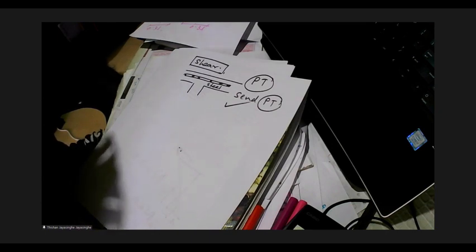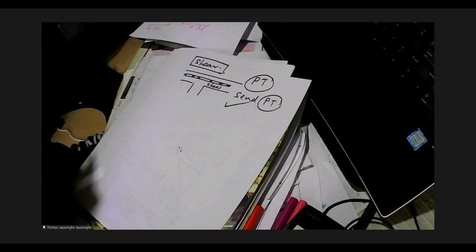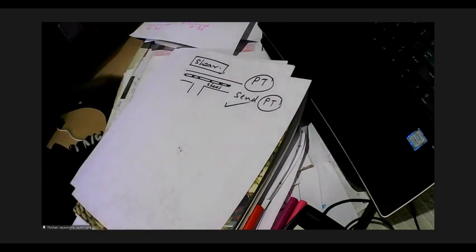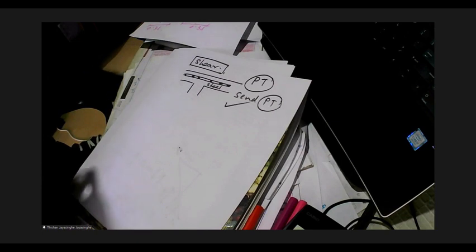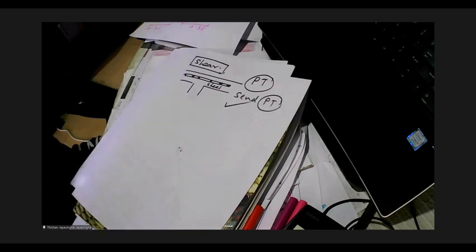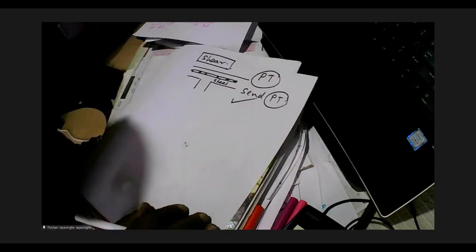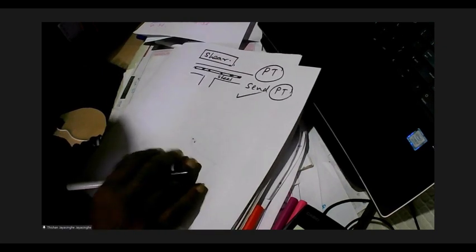If the stresses are too much due to live loads and other permanent loads, then put some reinforcement at the locations which are needed, and then you will prepare a drawing and then send it to the PT company and get it checked by the PT company, because they generally give that service as part of you purchasing their pre-stressing system for construction. So they provide that facility because they have the sophisticated software that can check the system. Is that clear, Bashika?